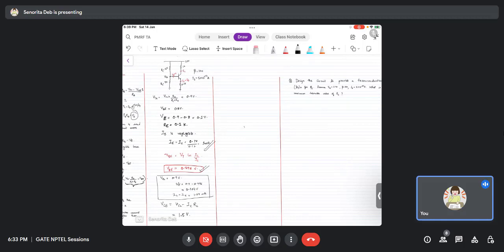So the emitter resistance is usually incorporated to make the common emitter amplifier circuit more stable. Since everything has pros and cons, and in analog, if something gives you some profit, you have to compensate for that as well. The compensation is that in amplification the gain actually reduces, but we have methods for that also. We will see that in the amplifier section. So as of now you can understand that the common emitter amplifier with emitter resistor gives you the best possible stability.